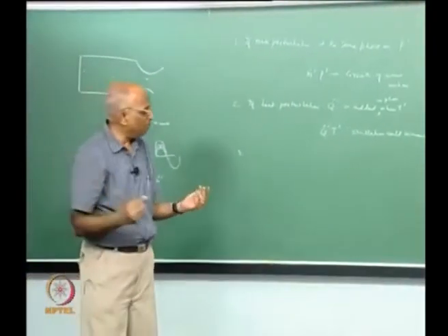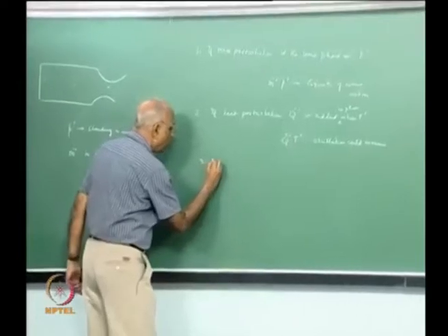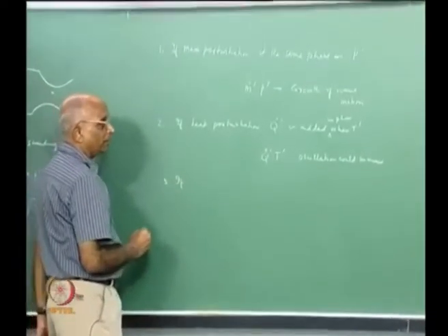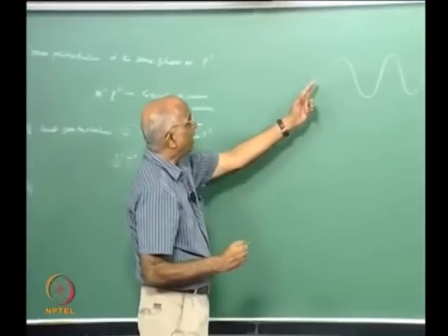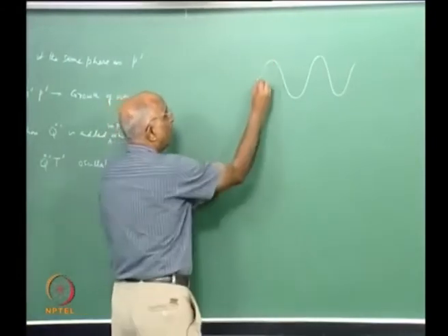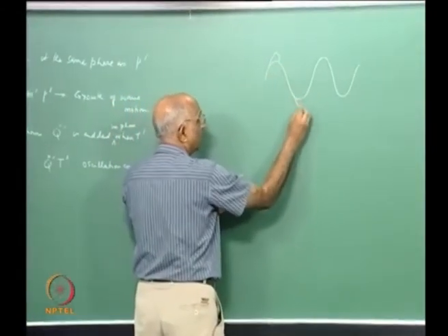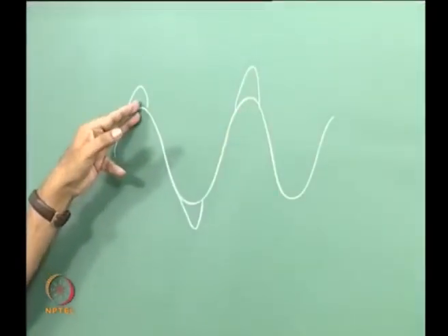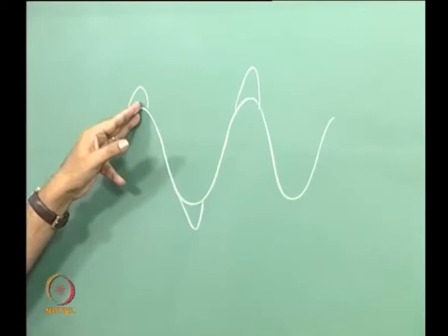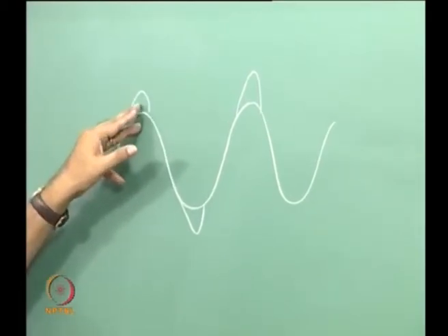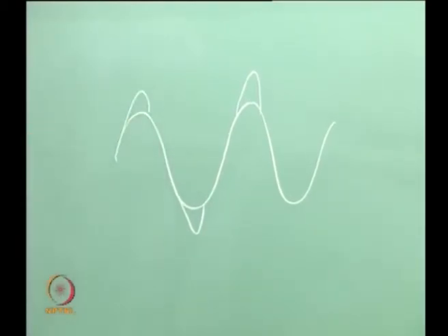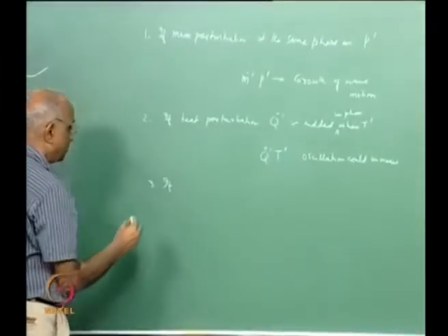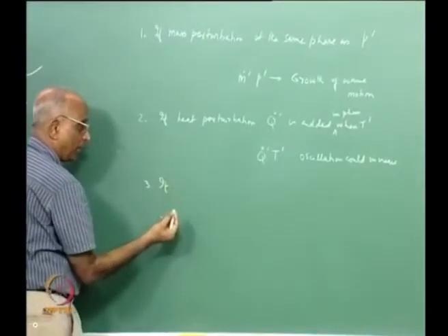Velocity perturbation is V prime, therefore if the rate of change of momentum, at this point I put more momentum into it, it could increase, here I remove, here I add. That means if the rate of change of momentum could be put in phase with velocity perturbations, then my velocity perturbations could also increase.